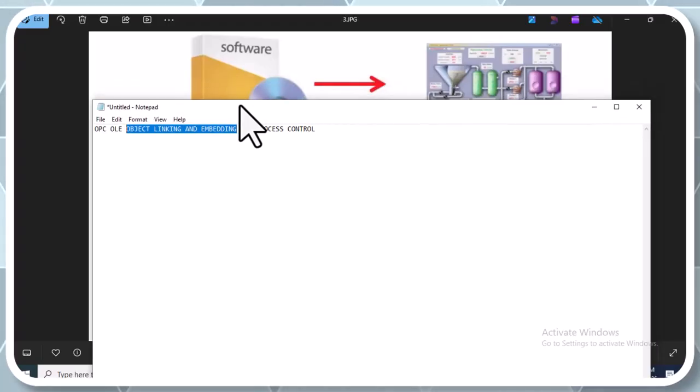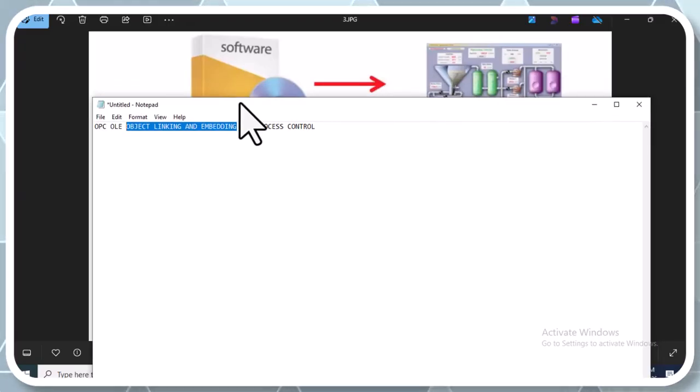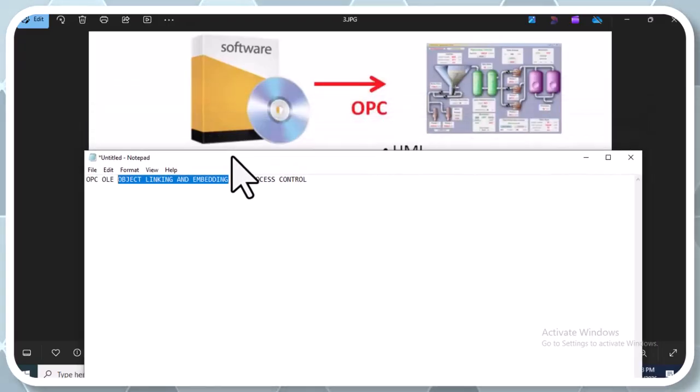And my friends, the last thing I want to explain, maybe you know about it, is the question of how the OPC server actually gets the data. It's a very common misunderstanding. Many beginners think that the PLC somehow speaks with OPC, and it doesn't.